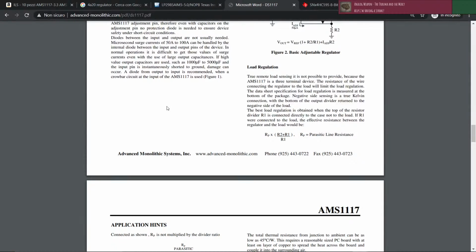Because if it's really sensitive, well, in theory you should match the impedances, but yeah, that's something that I don't know. Well, you should have the output impedance of your splitter be equal to the input impedance of the fuzz factory, so you have the maximum power transfer. That's something that I remember about this, because we only did one lesson about this, and we never used it in a lab situation. We only did stuff with NE555s, LM741s, and that's it.